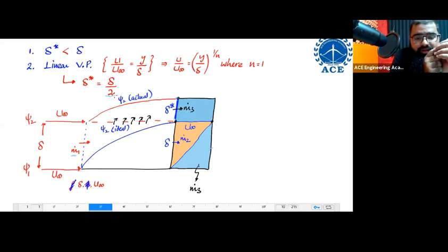I hope things are clear that m dot 2 and m dot 3 are individually less than m dot 1. Combined, they should be equal to m dot 1. M dot 2 is allowed to move forward. M dot 3 is not able to move forward, and he is not accepting that. He still wants to move forward. The only way out for him is to push this streamline psi2 up, so that psi2 creates some kind of distance. The distance is our subject right now. Once he sees the distance for m dot 3, then he can move. The distance is delta star over here.